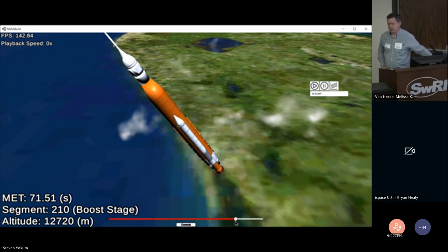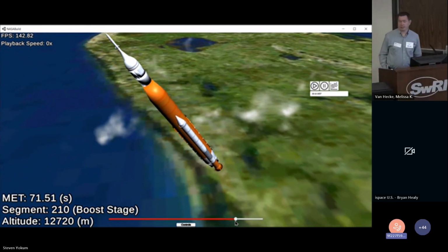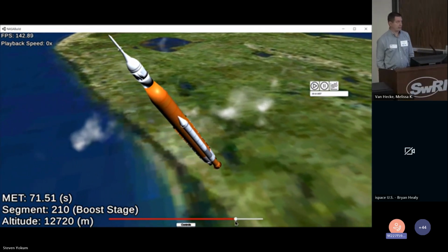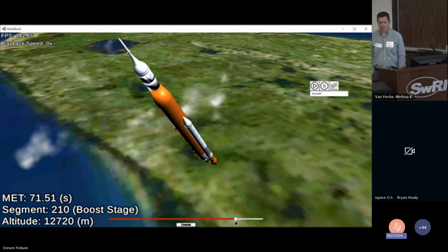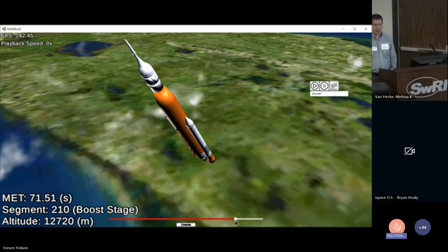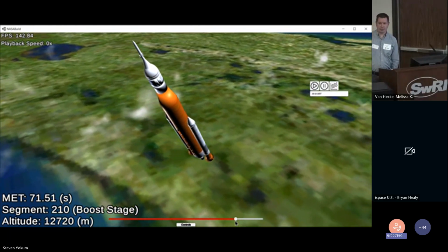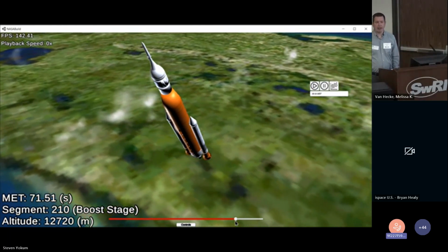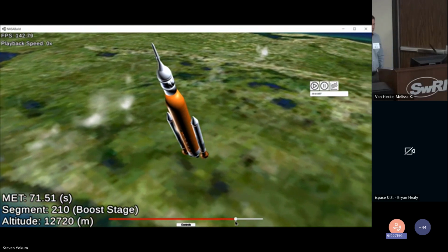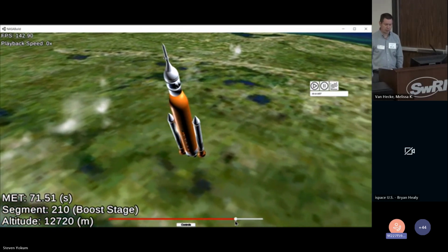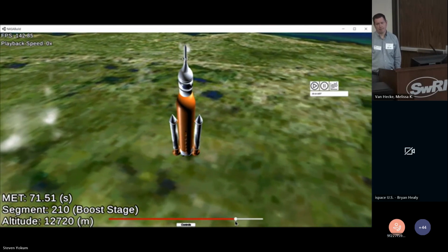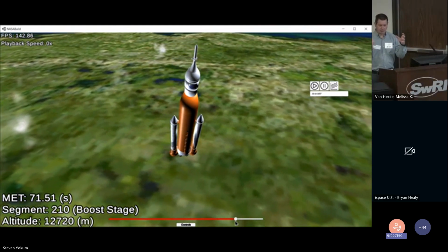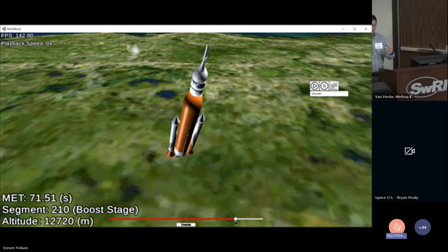The interfaces are fixed. When we get the flight computer, speaking to SLS, the only interfaces it has are the 1553 bus and 422. So whatever sits on the other side of that, I don't really care. I can talk 1553 and I can talk 422, so I can support those interfaces. Got it. So I'm only constrained by those buses that attach to flight software.